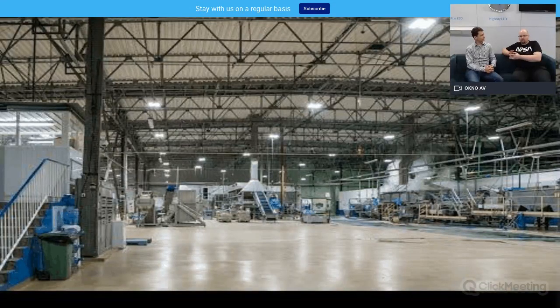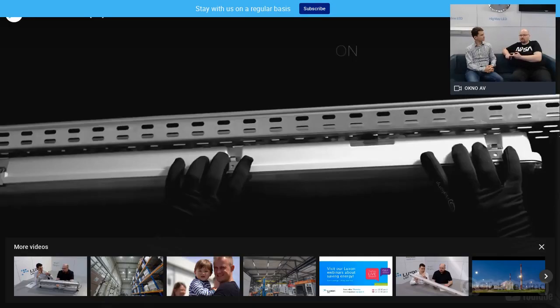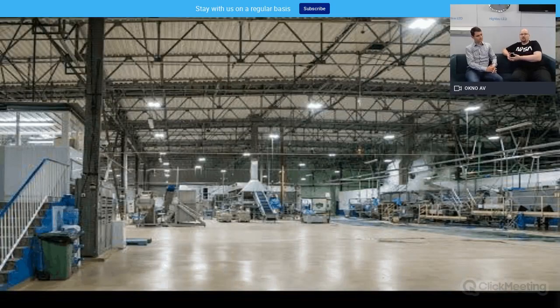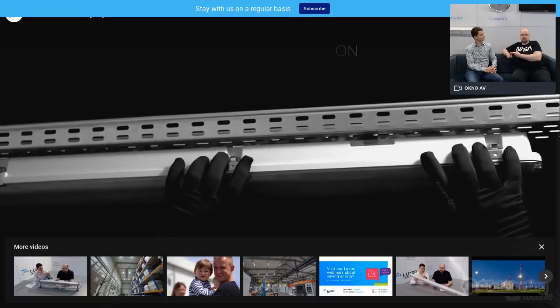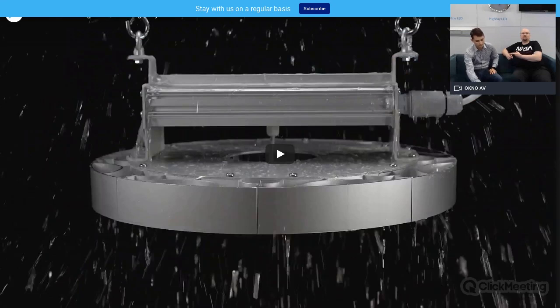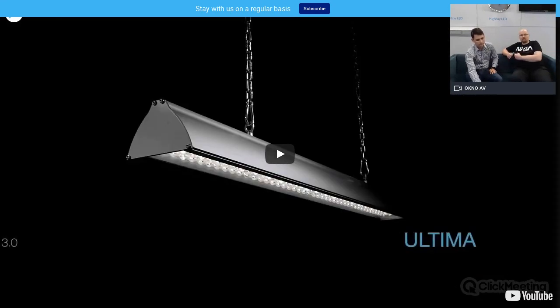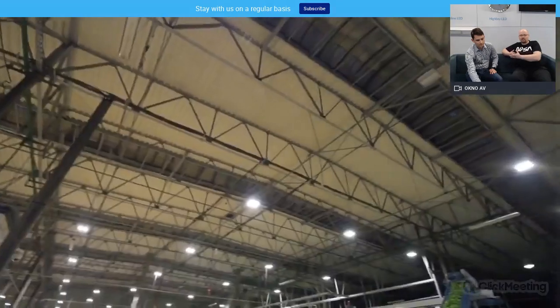In this case, we have to look a little bit back at the previous technologies. Previous technologies such as fluorescent, mercury vapor, or metal halide were discharge type light sources, which don't like low temperatures, especially negative ones. If you are below zero, they cannot reach lighting levels in the specified time. So you have to wait even longer than normal for this kind of light source to reach full brightness.